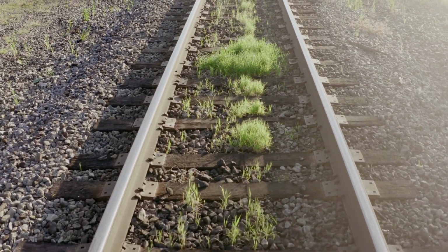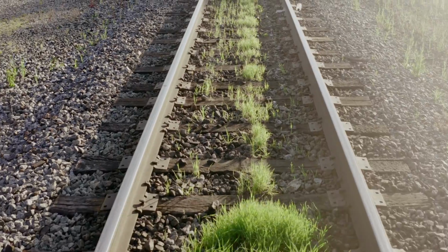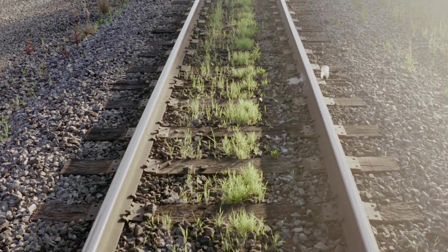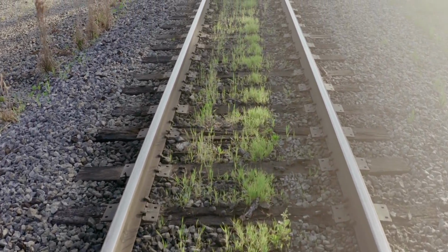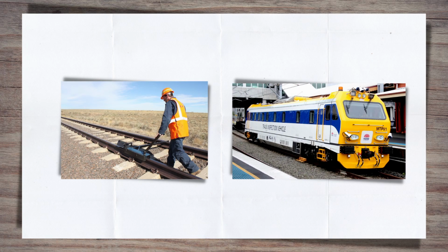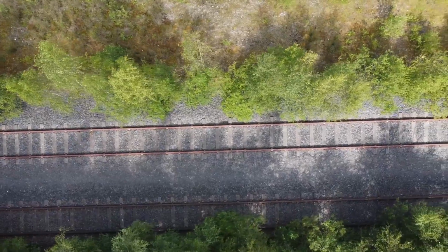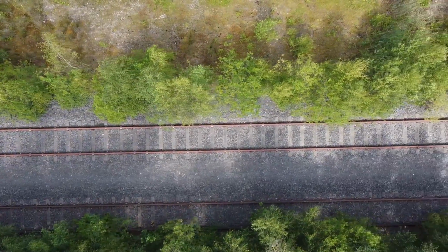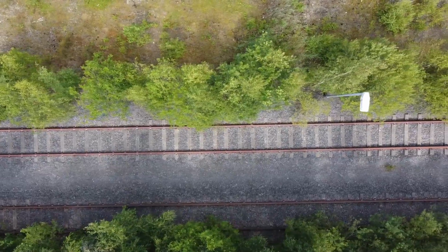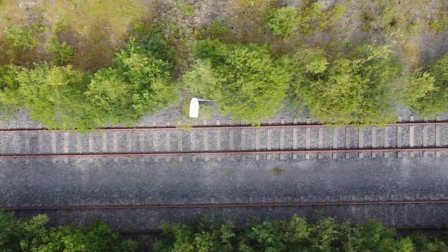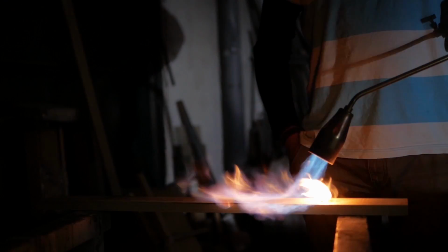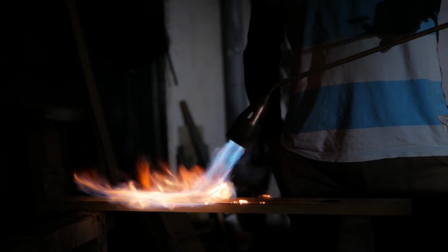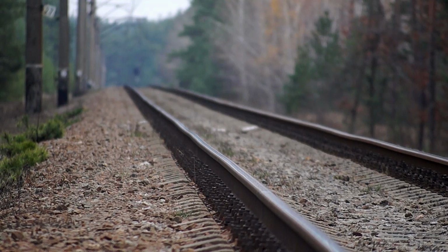As with any defect, being able to detect then monitor its deterioration is key to managing the risk posed by it. The use of both train and hand-borne inspection equipment allows large areas of rail to be inspected and the sites of RCF identified. Specifically, a process known as eddy current is very effective for detecting these surface cracks. One of the challenges of RCF is that if re-railing is required, the amount of rail that needs replacing can be extensive. This is because welding rails with RCF can cause the cracks to increase in size when the heat is added. So unaffected areas or areas of light RCF need to be found so that the welds can be installed.